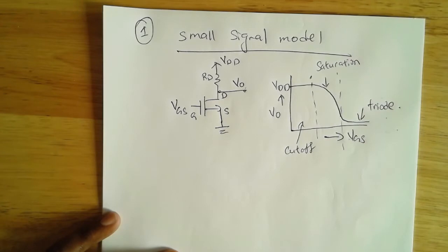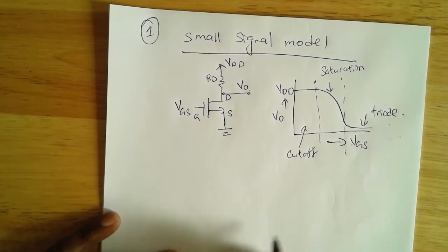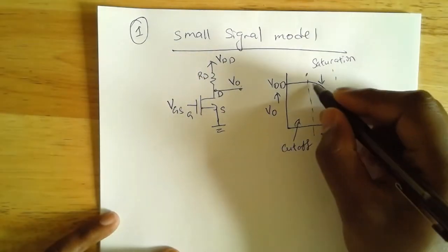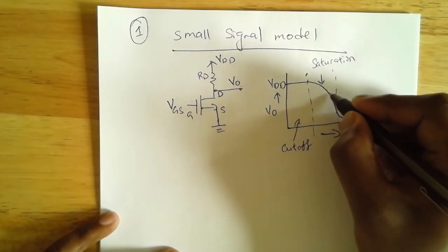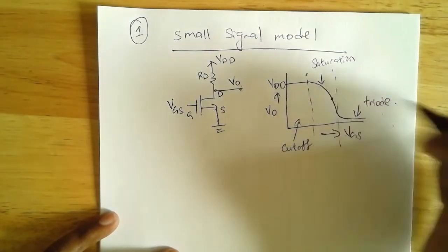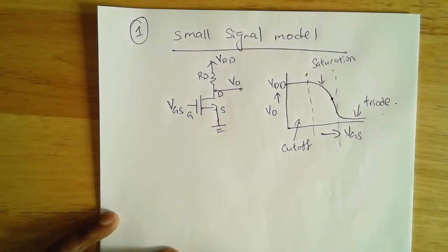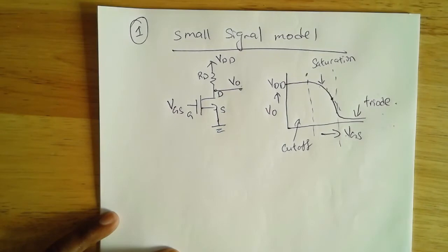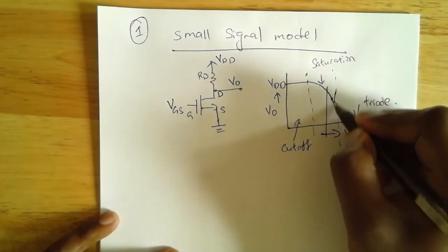What we talked about for making an amplifier out of this is we said we will look at the slope of this curve at each point, and we'll choose a point where the magnitude of the slope of the tangent is equal to the gain we want. So we'll fix our DC point over there, and we will change our AC input.